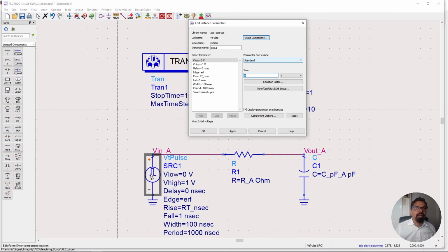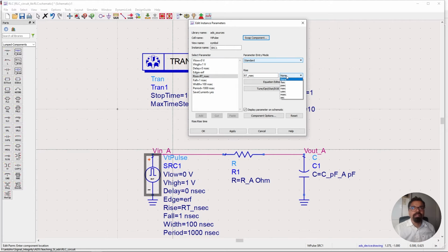Whenever you have these types of mistakes, it is very important, because we can't always trust the simulation. So here's number one issue. I've not basically said that this has to be in nanoseconds. So it just put in 1 and I'm not too sure what the 1 was. So the unit is important.